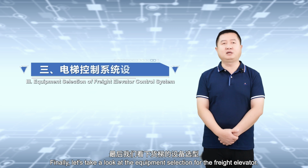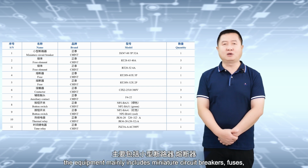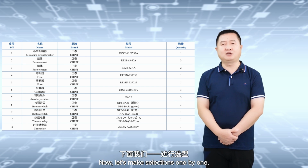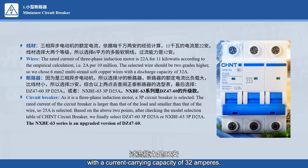Finally, let's take a look at the equipment selection for the freight elevator. As shown in the table below, the equipment mainly includes miniature circuit breakers, fuses, contactors, button switches, and thermal relays. Now let's make selections one by one. Miniature circuit breaker: we choose a 6 square millimeter multi-strand copper core cord with a current carrying capacity of 32 amperes.